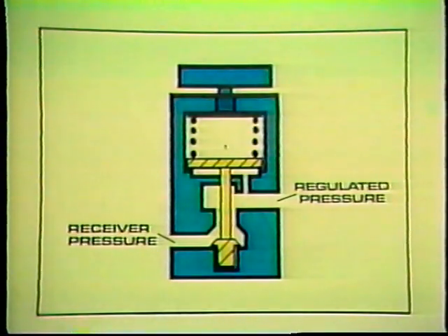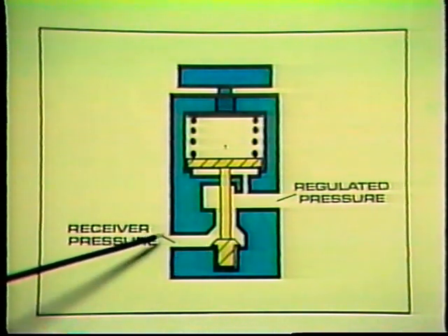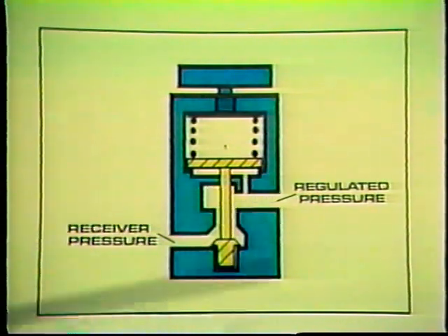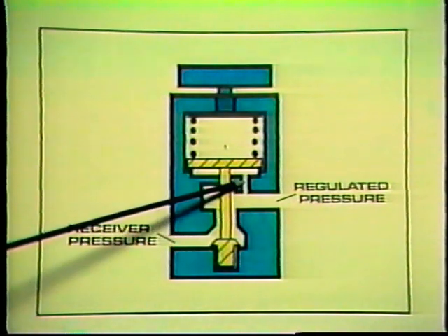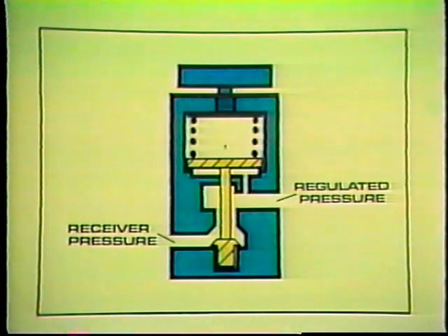The pressure regulator is a normally open valve, which means that the poppet is positioned, as you see, so that air can flow freely from the tank through this passage and into the circuit. When pressure rises, it is transmitted through the internal pilot passage and pushes against the surface of the piston. Because the piston has a large surface area exposed to the secondary pressure, it is very responsive to pressure changes in the output side of the regulator.